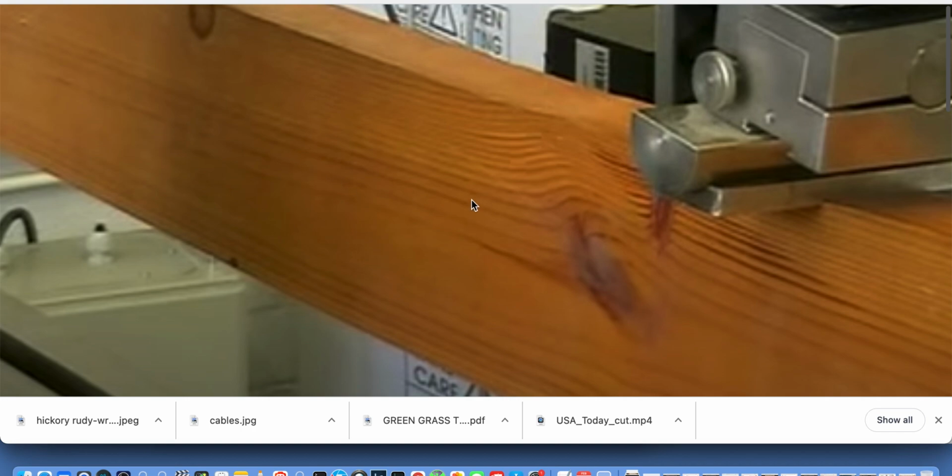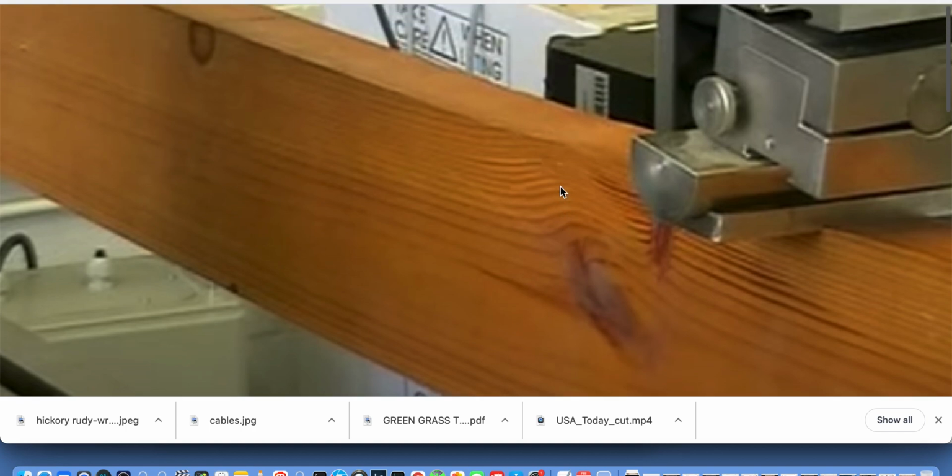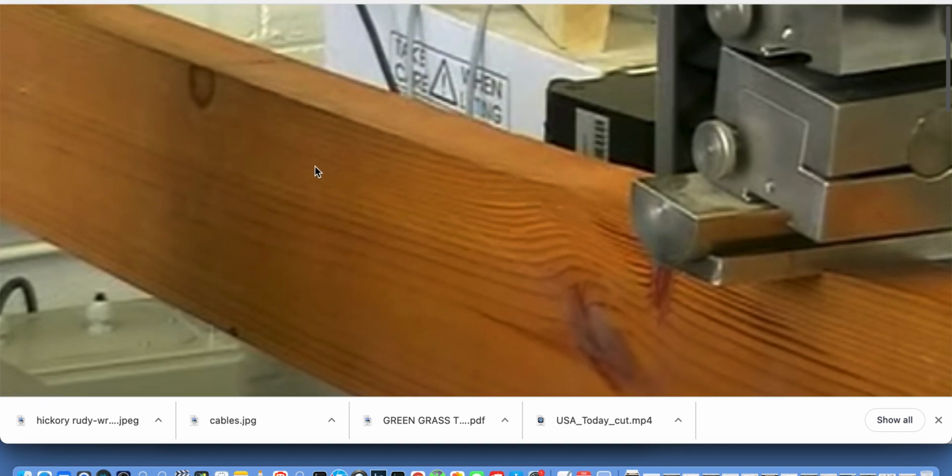It's like having stirrups, and then they divert around and come this way, and it's like a defect in the stirrup design, if you will, with loading. And so when I look here, I see that the grain structure goes this way and comes up and disappears into space. So that means when this gets stressed, this is where it's going to want to break.